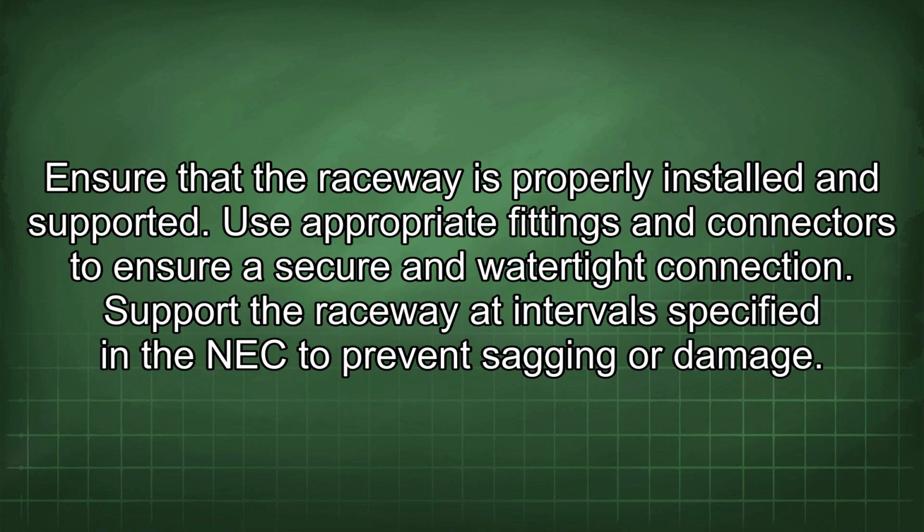Ensure that the raceway is properly installed and supported. Use appropriate fittings and connectors to ensure a secure and watertight connection. Support the raceway at intervals specified in the NEC to prevent sagging or damage.